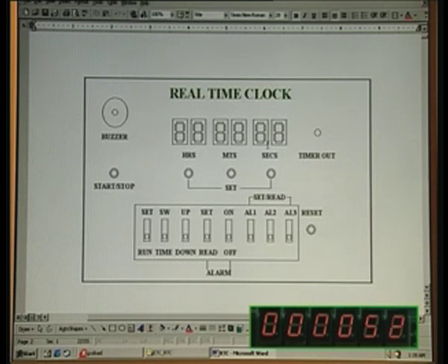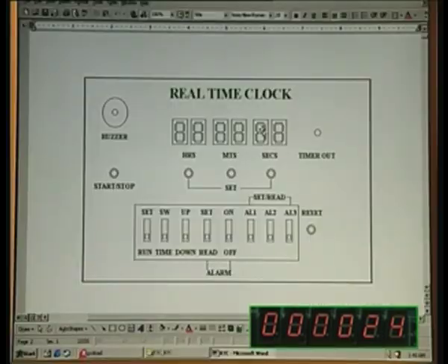In order to relieve your burden, what we do is you just press once and hold it. Having pressed once, the code will recognize and advance by 1, and then it will continue to see whether you are continuing to press for 2 seconds and more. If it is beyond 2 seconds, it will start running at a very rapid pace. Automatically it will roll. So, it will advance 10 times faster. For example, this will become 1, 2, 3 every second instead of this one. So, you have a provision of setting fast.